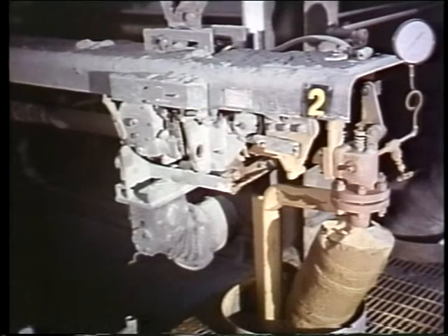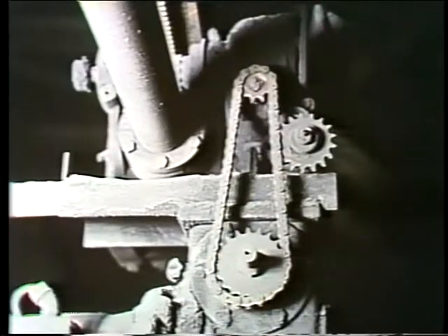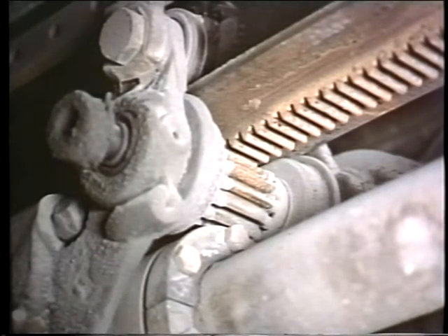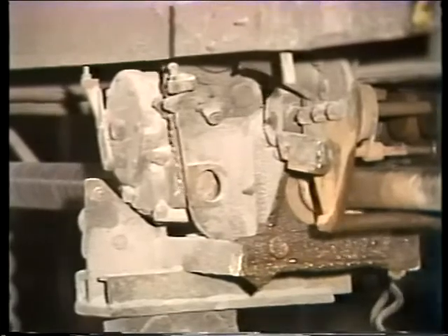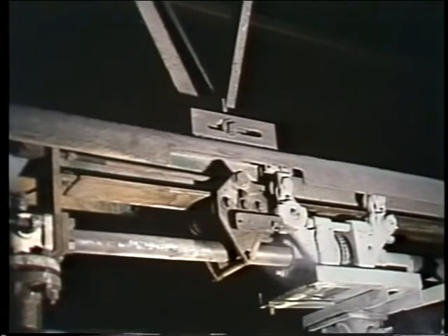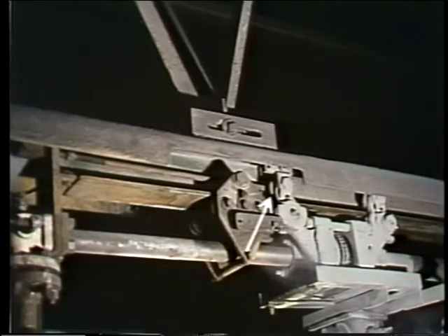The traveling drive mechanism in our example has its drive motor on the carriage. The motor drives the carriage through a chain and sprocket that turns a pinion gear. The pinion gear meshes with a rack mounted to the support rail. Rotation of the element is driven by chain from the same motor. As soon as the element travels far enough to enter the boiler, the valve trigger mechanism is tripped as the carriage goes by. As the element rotates going out, the soot blower cleans a helical path.